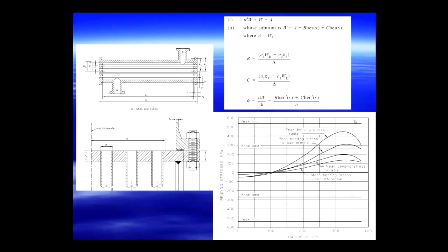In a standard tube sheet, drilling the tube sheet is often as much cost as the rest of the vessel put together. Huge amount of drilling time, drilling through really thick tube sheets. With this advanced analysis, I was able to show that the thing was perfectly safe with a nice paper-thin tube sheet. And there's the analysis as it came out of the system.